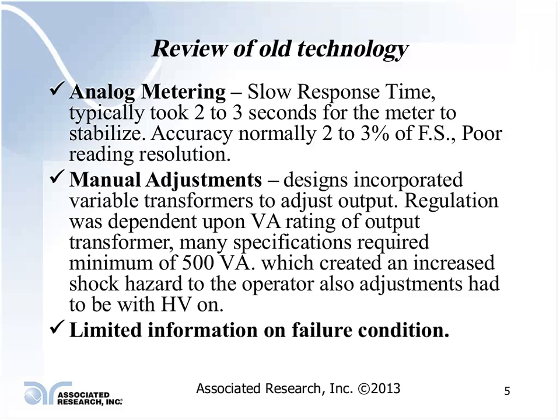What do you mean by full scale? Well, if your instrument is capable of producing 5,000 volts and you had a 3% accuracy, which was typical for an AC Hipot tester, you were talking about 3% of 5,000 volts. So that was anywhere across the display. So if you're looking at a 5,000 volt reading,